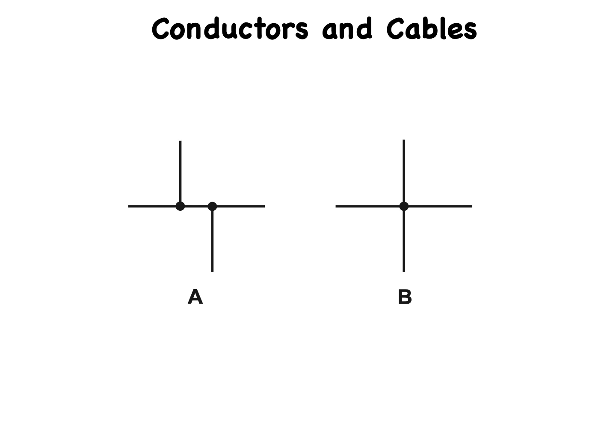In the drawing at B, the 2 conductors cross, at right angles in this example, and a single black dot is drawn at the junction. This dot tells us that the conductors connect at this point. The method shown at B might look better at first glance, but the neatness comes along with a problem. Some readers might overlook the black dot and think that the 2 conductors are not meant to connect. The method at A makes that potential misinterpretation impossible.